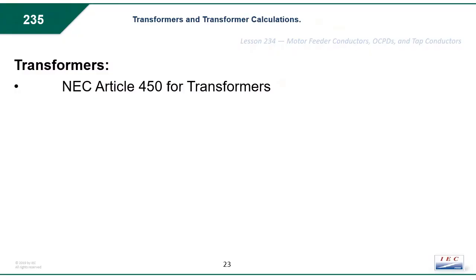Also for transformers, NEC Article 450, anything regarding transformers, the sizing of a transformer vault, what's the fire rating of a transformer vault? All of these are found in Article 450 when you're doing your keyword searches.